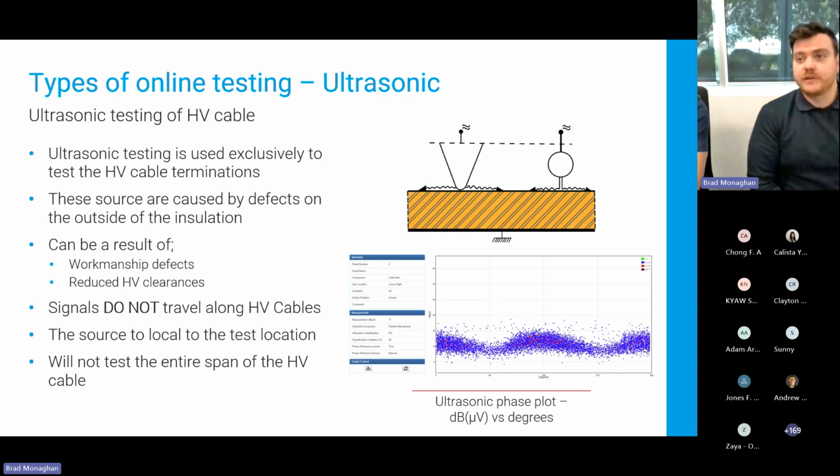So what is possible? There are a number of different tests that are possible when you look at online partial discharge testing of HV cables. The simplest is ultrasonic testing, and ultrasonic testing is looking for surface type tracking, electrical treeing, but it is only really testing your terminations. Because as I talked about in the beginning of the webinar, the points where we're really looking to focus are on your terminations at either end and your joints along the cable span.